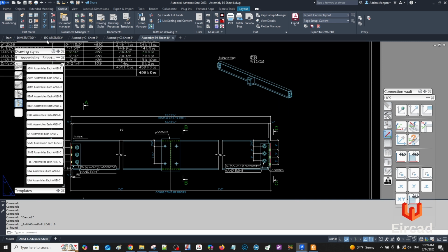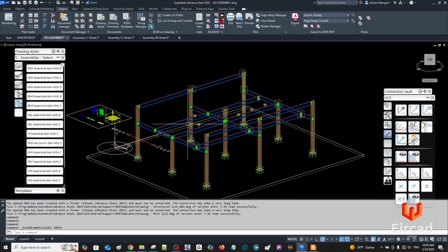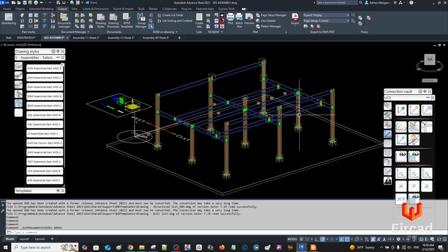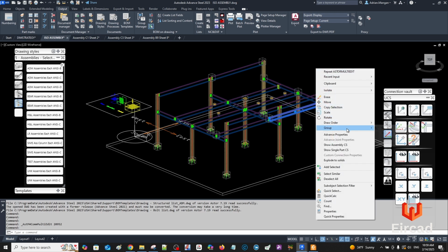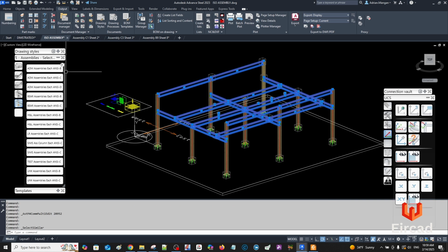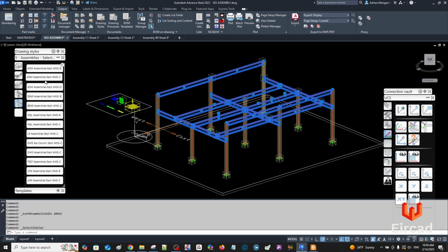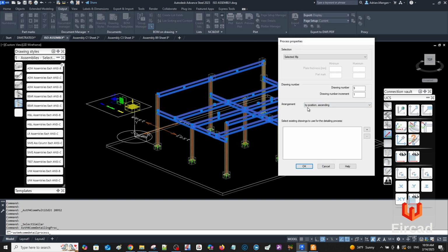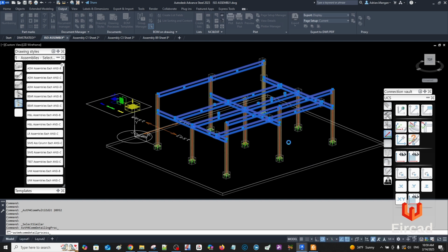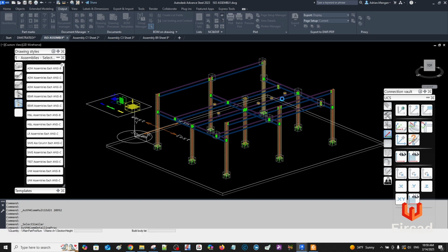And then it's just a matter of, you're probably going to have two different drawing processes for the beams and the columns, so you can just select similar for the beams or use a query, select all those, and then just output those. Now, right now, the beams should all come out with an isometric, so we'll just randomly pick one of them. We'll pick this one here in the middle,